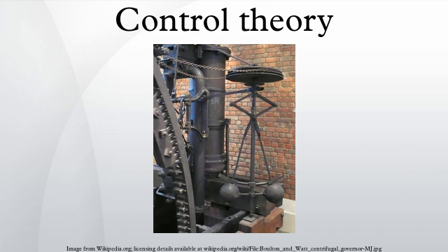Sometimes mechanical methods are used to improve the stability of systems. For example, ship stabilizers are fins mounted beneath the waterline and emerging laterally. In contemporary vessels, they may be gyroscopically controlled active fins, which have the capacity to change their angle of attack to counteract roll caused by wind or waves acting on the ship.